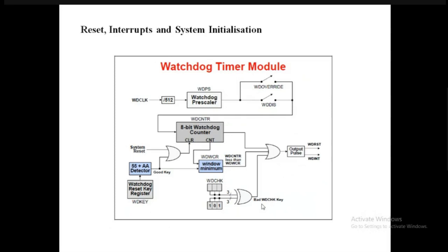But if a certain issue is there with your main clock and it is not able to run, then obviously your program will be interrupted. And in case a certain issue is there in your algorithm as well, this watchdog counter will not receive the clock from your main CPU, and then it will reset, and it will not allow your main algorithm to run. We'll see how this watchdog interrupt is triggered in the example as well, and then you will understand better what I was saying.